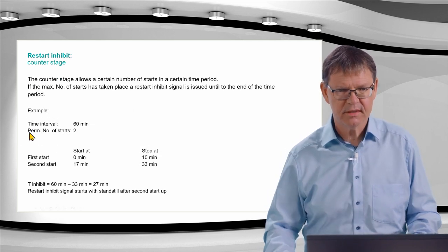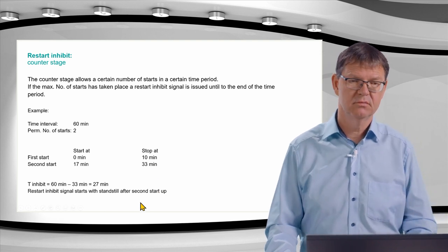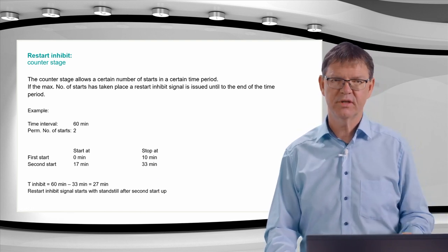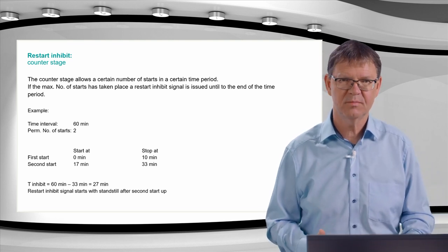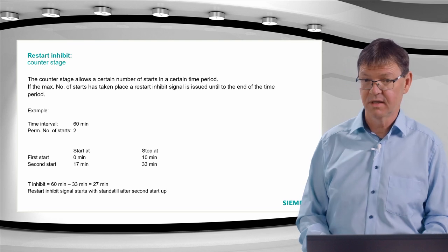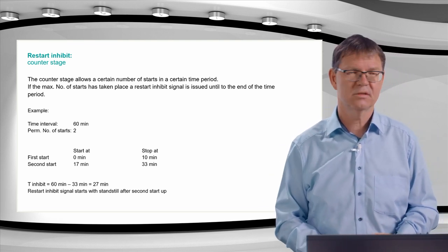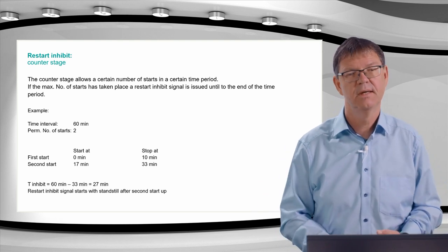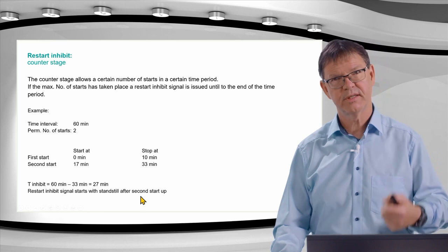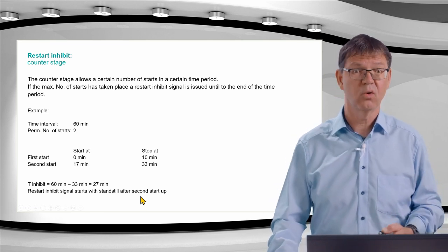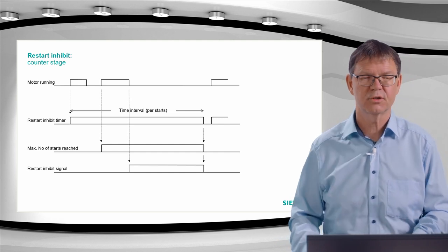Maybe I did not mention that. I always have the possibility of an emergency start or restart via a binary input. So if thermally I would not be allowed to start because it endangers the rotor, but from the process point of view I need to restart a motor because something else more severe happens, then I can override all that, and with a binary input I can of course restart the motor nevertheless. So this option is always there for all of these thermal functions.